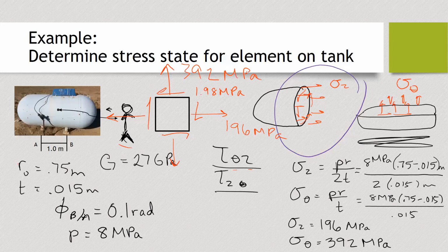One is, if you have, say, this section cut, and say that's point A and that's point B, and we know that the torsion must be going in that direction because that's how you get the counterclockwise rotation of B relative to A. On this near side, that torsion creates a shear stress that goes in the same direction as the torsion. It's then resisted by the reaction, which would be on the back side.